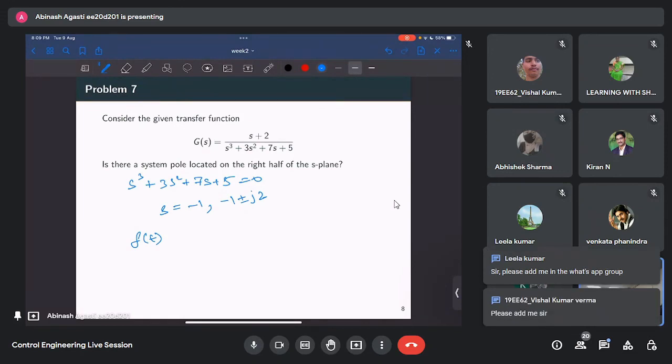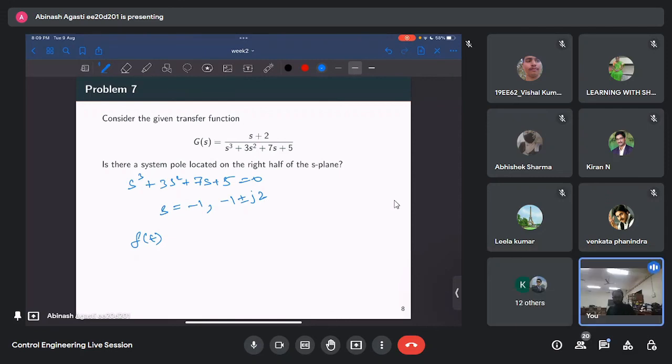in control system problems, what you will see is I applied a step input. What that means is I switch on and it instantaneously goes to some value. But in reality that will never be the case, right? So there is always some kind of delay. Or say suppose I have some circuitry for some machine, I switch it on, there is some circuit delay within the machine, and then that propagates, like that adds kind of a delay to the actual input or impulse into the system. Okay, so I guess that is the meaning of transport delay.